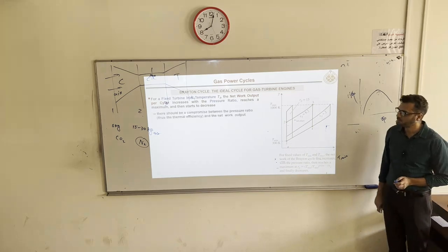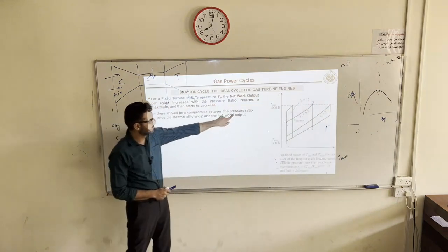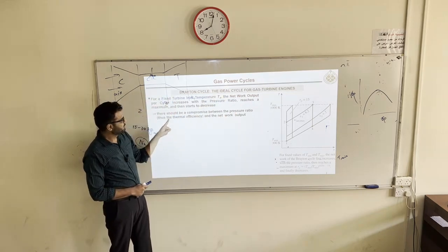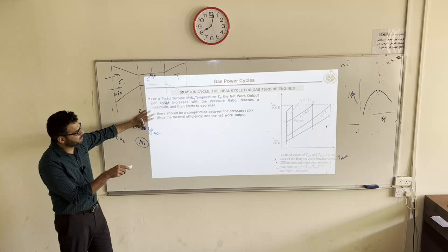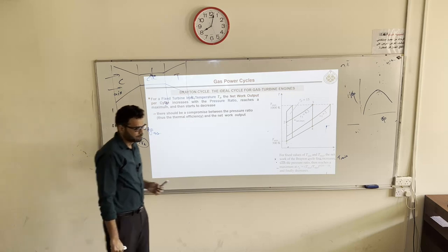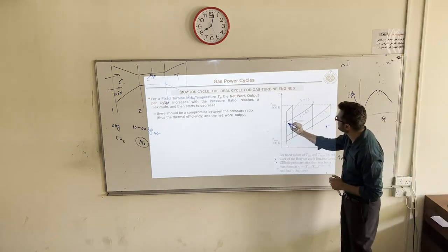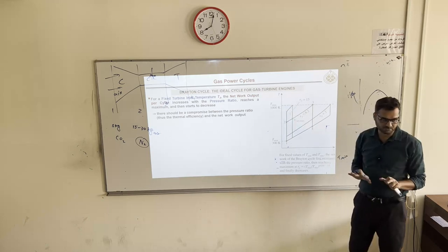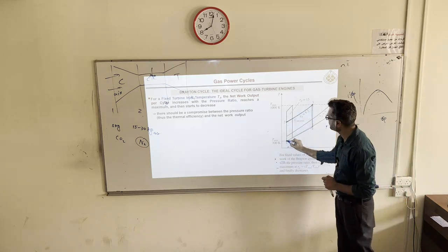Okay. So it means there are three things which we have to take into account: pressure ratio, how much pressure ratio we can raise. At the same time, we have to keep T3, and also the net work output. So there should be a compromise between the pressure ratio, which of course is affecting thermal efficiency, and the net work output. Okay, if you want to get maximum efficiency, for example, this gives us maximum efficiency. If you further increase pressure ratio, we get lower efficiency. Okay, so it means this is the maximum I can get from what?